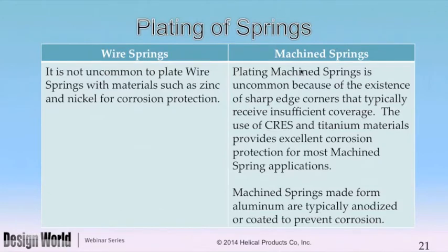Plating of springs. It's not uncommon for wire springs to be plated with zinc, nickel, maybe even copper too. And that's good. Machine springs can be plated, but there's some problems. If you remember looking back at those pictures of them, on the coils there are sharp edges. And plating of anything that has sharp edges on it has a problem right at the edge, because there can be a small electric charge there, and the plating process just doesn't function well.